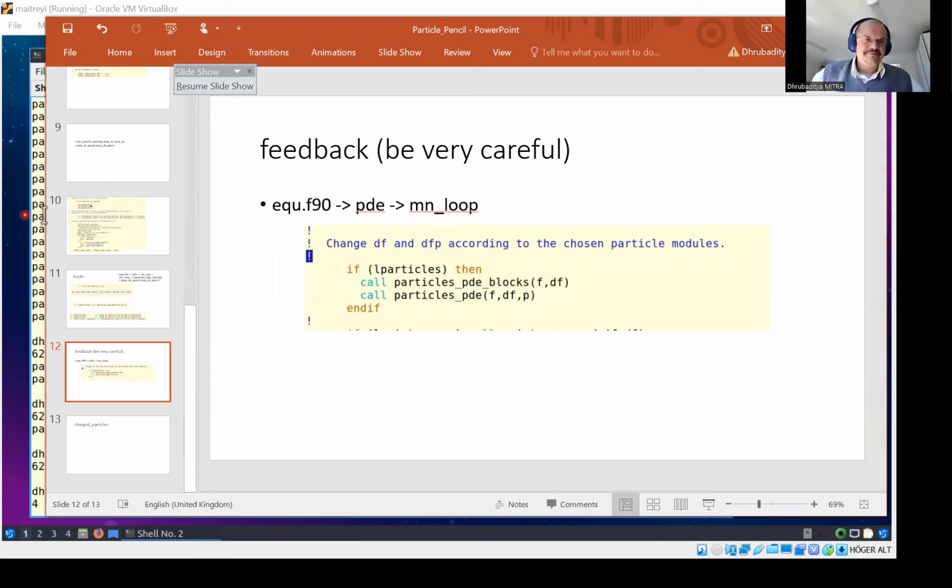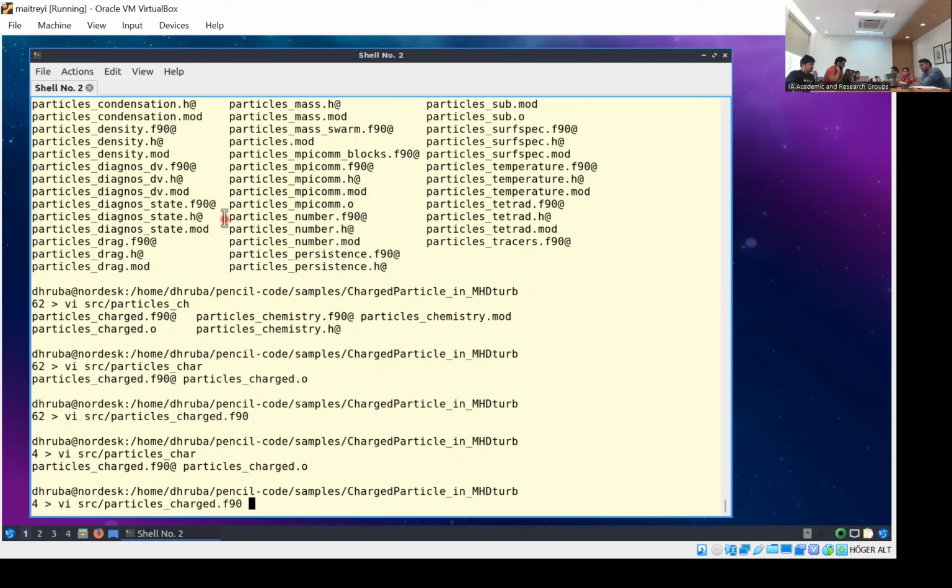So the time step is controlled. Yes, and I can show you where. So let's see. So you see the Courant condition is not really always the excellent estimate. Your code can be still messed up even if you satisfy the Courant condition.